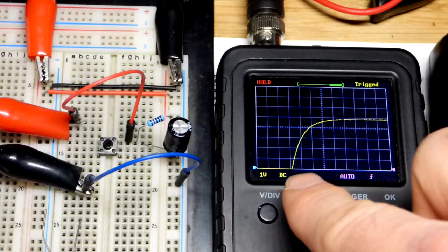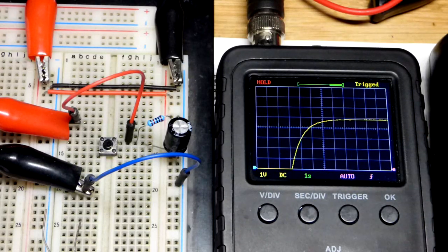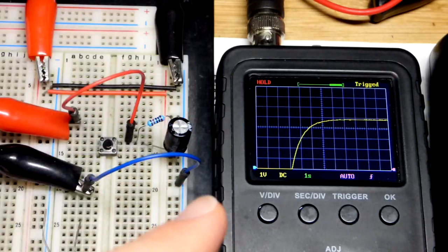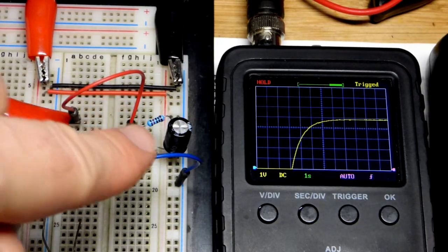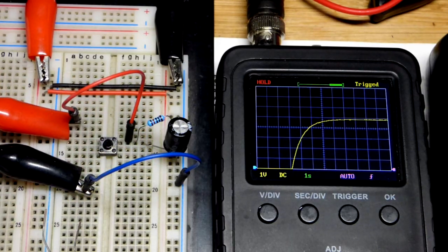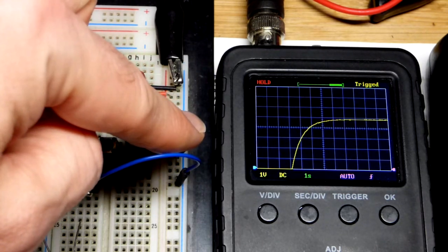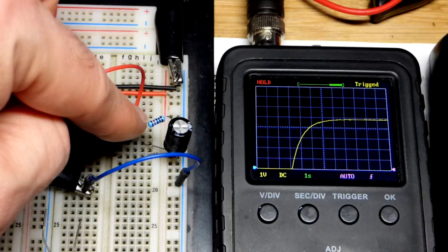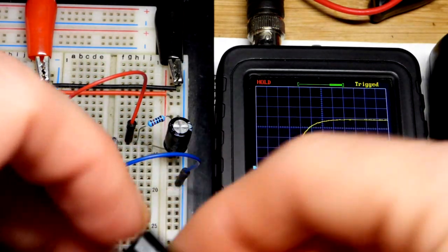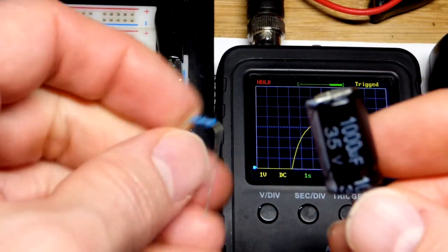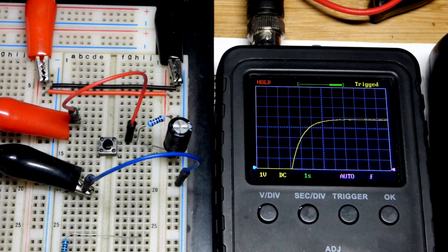And again, after 5, so in this case it's 1 second, but it doesn't have to be. You can adjust the values. Higher values will make the curve take longer, and lower value components, one or the other, it's going to go quicker. And so we lowered the capacitor by 1/10 the capacitance, and then raised the resistor by 10 times the resistance, so it equaled out when compared to when we used the 1000 microfarad and the 1000 ohm resistor. But we're just keeping the math easy in this video.